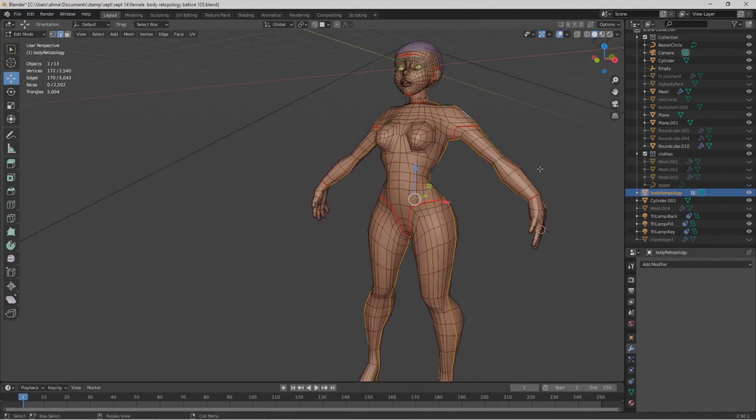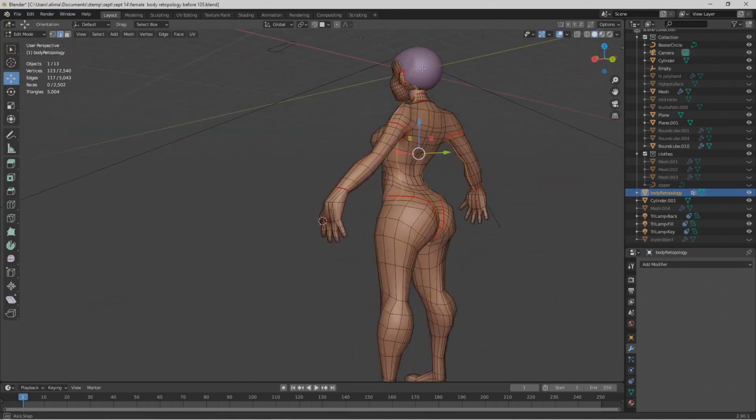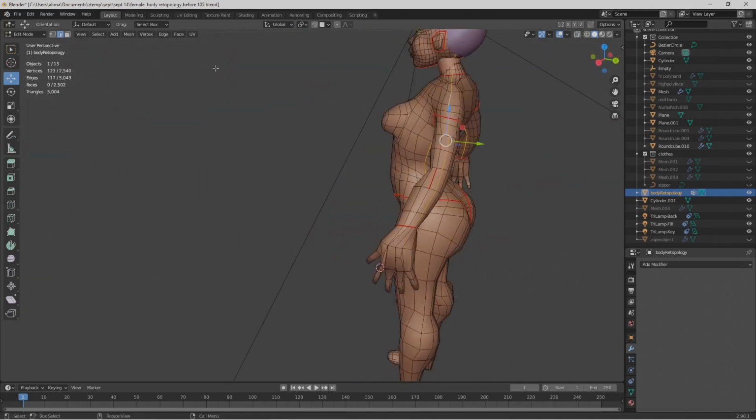Okay, so here I have what I want selected, but then also geometry that I do not want selected. So I'll go to the upper right, select Toggle X-Ray. I'll press C for Paint Select. And then where I see geometry that I don't want, I'll deselect it. Right click, get out of paint select. I'll toggle the X-ray to go back. Zoom in.